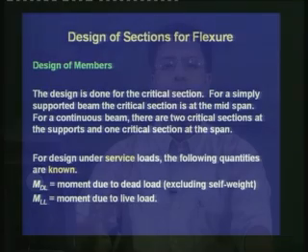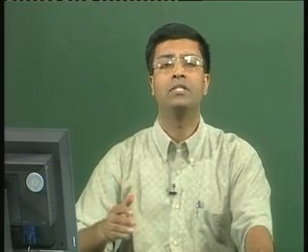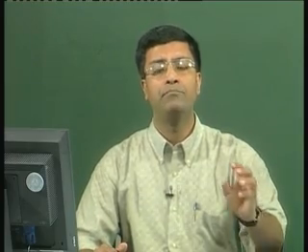Thus, from the analysis, which is either by the moment distribution method or by using the moment coefficients, we find out the moment demands at the critical sections, one for the dead load, which is represented as MDL, and another for the live load, which is represented as MLL. We may not know the moment due to self weight yet, because the section may not be available during the analysis.